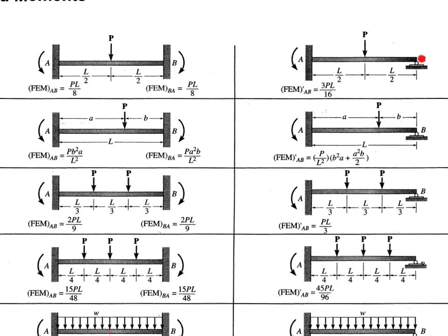What would this apply? A force back up. So if there's a force acting down, this will apply force back up. But this is called a pin or a roller. A roller is the term usually used. A roller support. It simply means that it's not embedded into a wall, so it can't prevent rotation. Okay? So for example, if this were to want to rotate, this would not stop it from rotating. This is what's stopping it from rotating. Yeah, or like a rolling pin. You'd roll dough and knead dough with. Same idea. It's a roller.